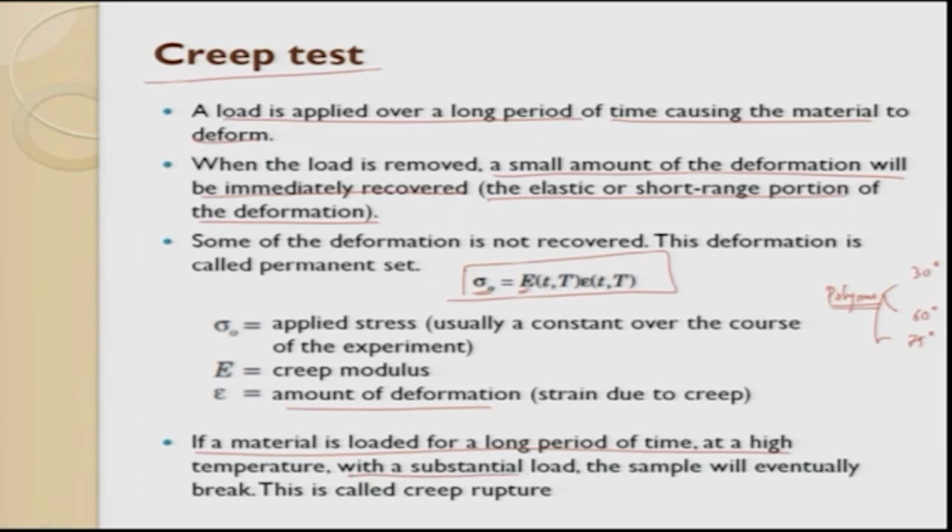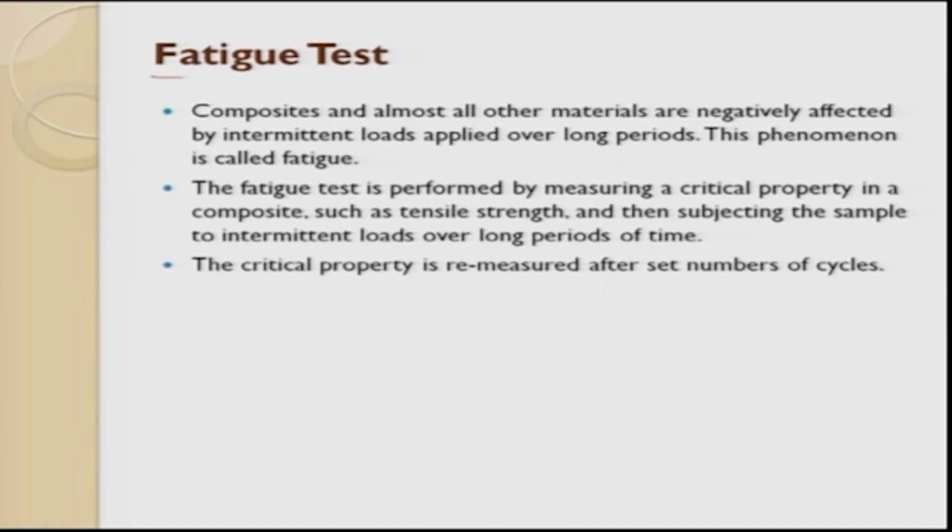So with a substantial load, the sample will eventually break, and this is called the creep rupture. So creep strength depends on time and temperature. The next one is fatigue. Till now, whatever we saw was static loading. Now we will get into dynamic loading.